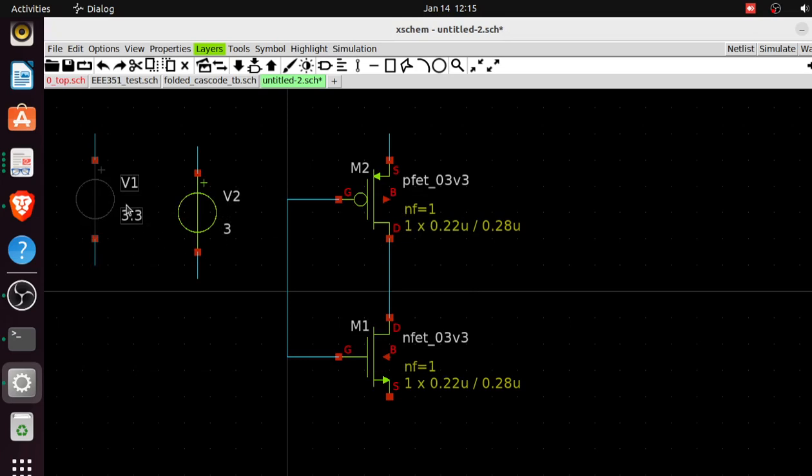So that's the VDD. And how do I know where to put the VDD? The arrangement matters. If you check the arrangement of the MOSFET, this is the PMOS. You can see the source, the bulk, the gate, the drain. For the PMOS in the CMOS inverter, the source is what is connected to the VDD.